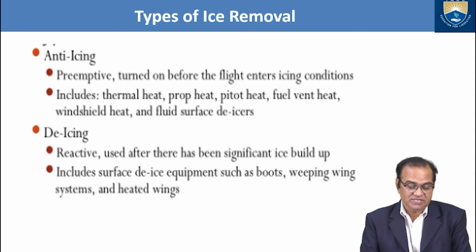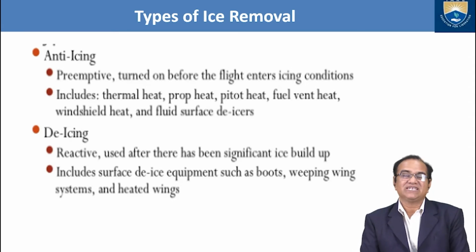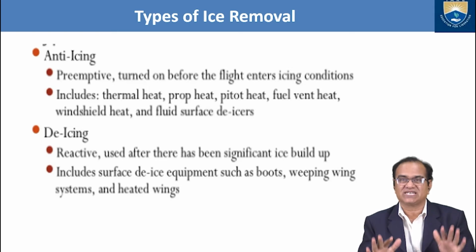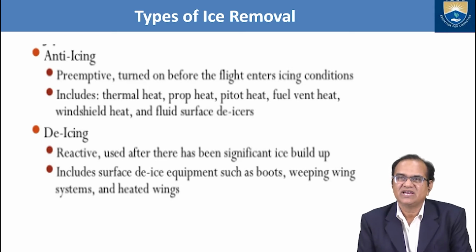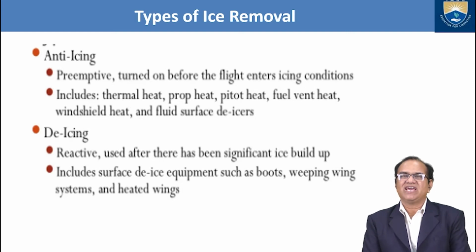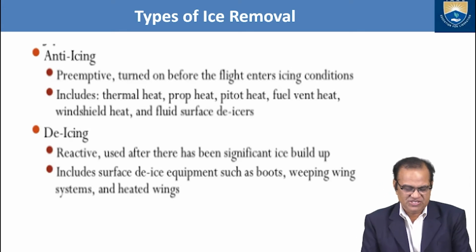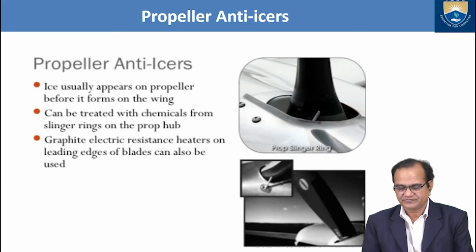Now de-icing is what? Reactive. De-icing is reactive, meaning you react after it happens. It is used after there has been significant ice buildup. It includes surface de-icing equipment such as boots, weeping wings systems, and heated wings.